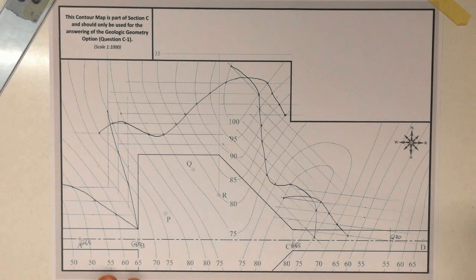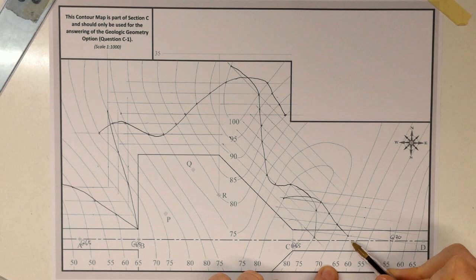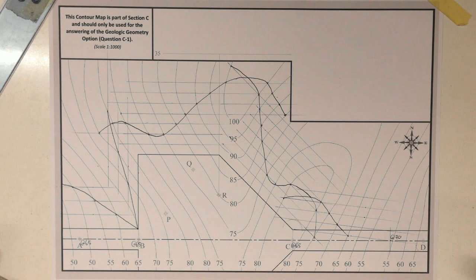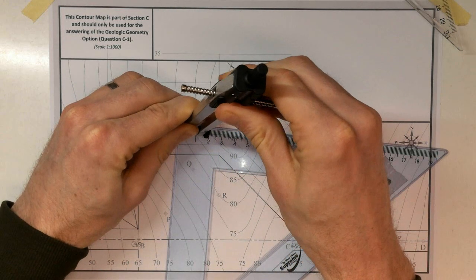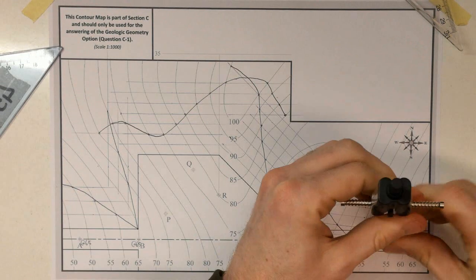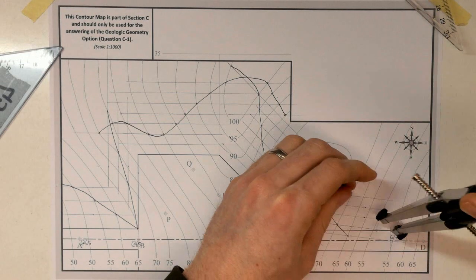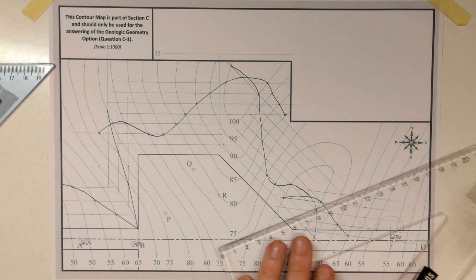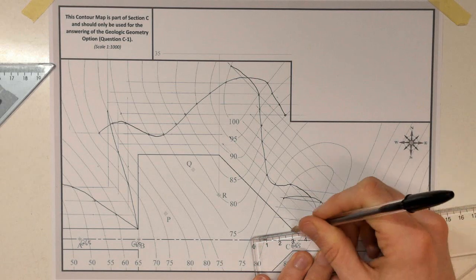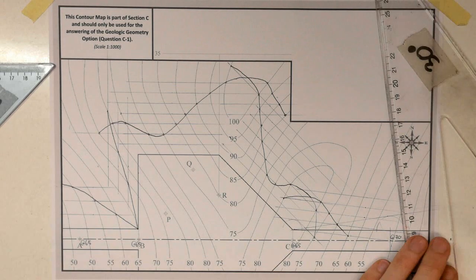So there. Okay. Now, once I hit the road here, you can see that we're underneath that level. We've gone from 70 to 65, so I'm going to have to fill in over here. So, the radius of my fill cone is going to be 10 millimeters, at 70. As you can see my cone there. Right, and then we're going to join that to C tangentially. Okay, we're going 10 millimeter intervals here.